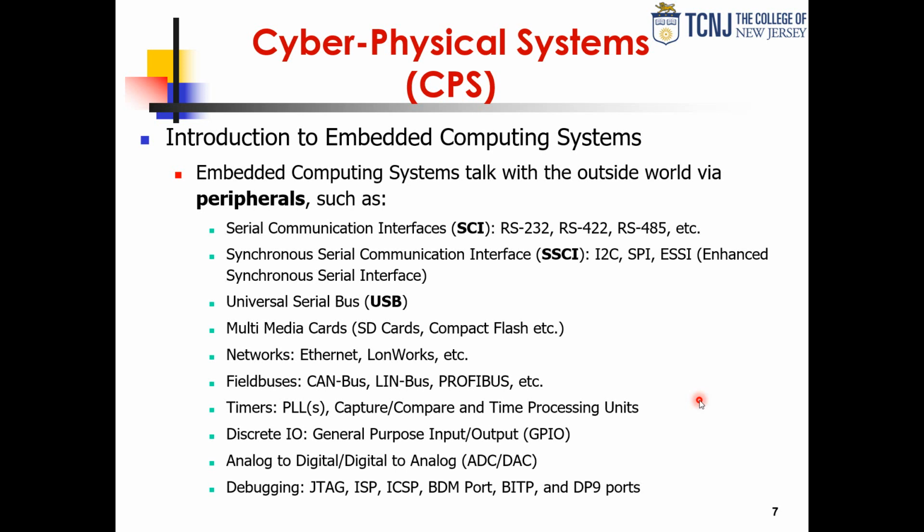And you have analog to digital and digital to analog conversion. These days you're also seeing some further integration of analog. I think that the PSoC architecture does a good job of integrating a little bit more advanced analog peripherals, but a lot of other vendors are starting to do the same thing. And you can get integrated temperature sensors, band gaps, op amps, comparators, and things of that nature. So those also look like peripherals in the embedded system computing element chip.